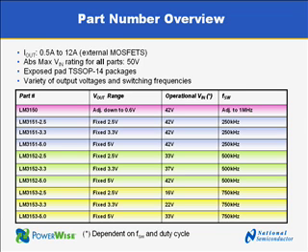We have versions with 250 kHz, 500 kHz, 750 kHz. And you will see here that in this part, for instance, we have an operational VIN of 33 volts. What is it? We have an output voltage of 2.5 volts at 500 kHz. Due to the constant on-time architecture, there is simply not enough off-time to have a higher operational input voltage than 33 volts.